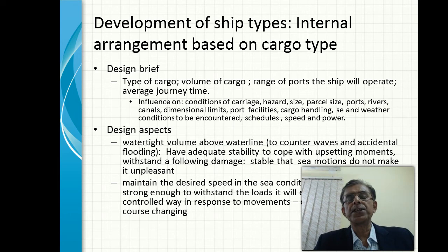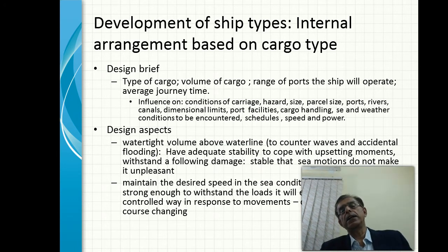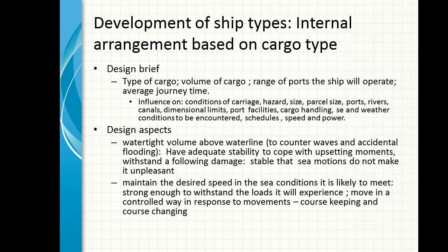must withstand that the ship must be able to float and have enough reserve buoyancy. It should be stable against various forces that cause it to roll and move in a seaway. It should maintain the speed which is designed, which the owner wants to achieve. It should be strong. It should keep the course, and it should be comfortable to reside on, and economically the ship must be able to ply as well as be safe and reliable. So there's a whole plate of requirements which the naval architecture subject has to stand. It starts with a blank slate almost.